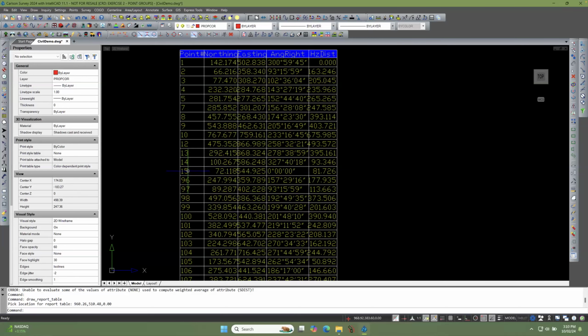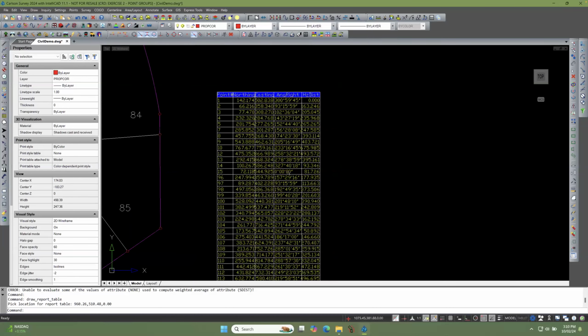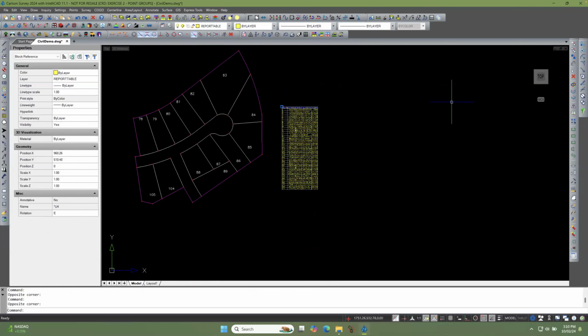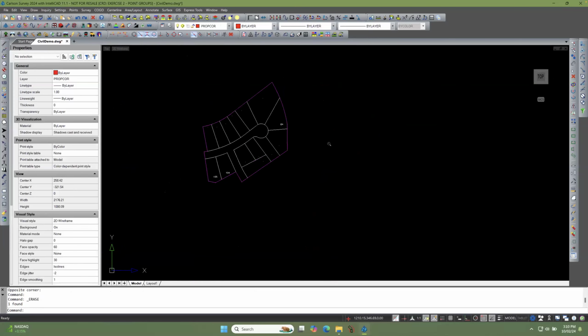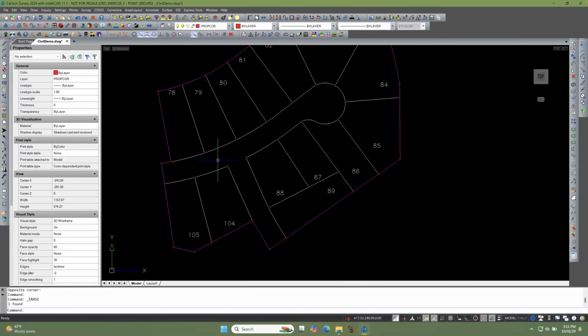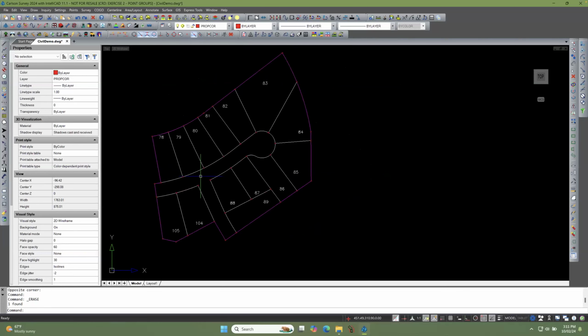So 1 looking at 2, setting 15, I have a 0-degree angle right. So apparently that's right on line, 1 to 2 to 15. Okay. So all of that from using point groups judiciously, and you'll be able to then send those out, put them on a data collector, and they can go out there and stake the points. And you're not having to go in and click the endpoint, the endpoint, the endpoint, the endpoint. You can just do it all very quickly using those points.